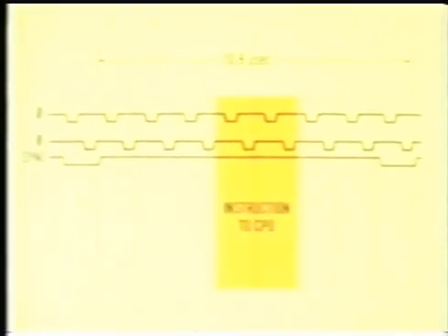The 4004 fetches and executes instructions using an 8-step cycle, which takes place in 10.8 microseconds. The 8 steps involve 3 for transmitting the 12-bit address to the ROMs, 2 in which 8 bits of instruction are returned to the CPU, and 3 steps for execution of the instruction. Instructions are either of 1 or 2 bytes.